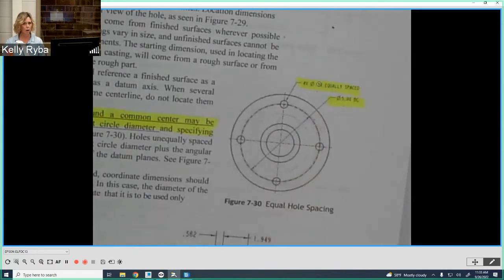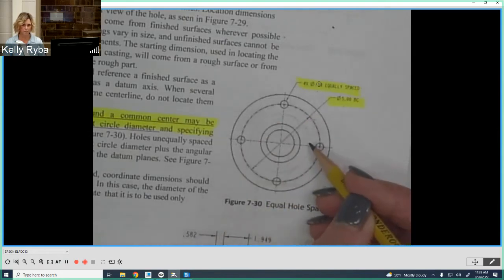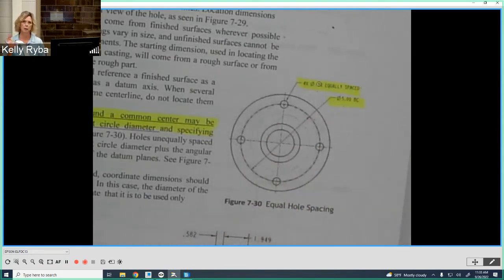So you can put it all on one note because you're already showing that diameter on there. As long as you show the center line circle going through all of those points, you can see that that's the circle that it would be on. So you can either get it at one note, or you can get at it by 2 separate notes here.